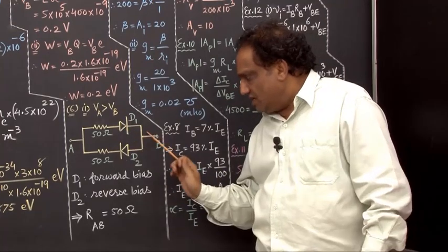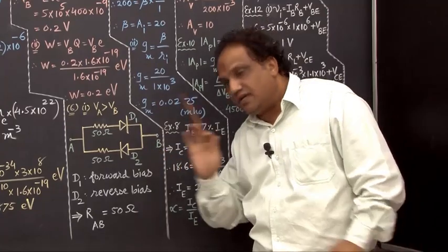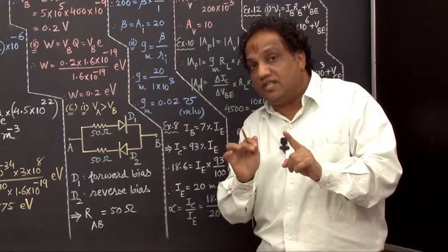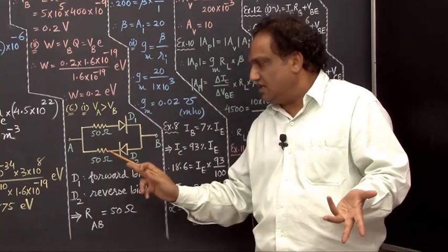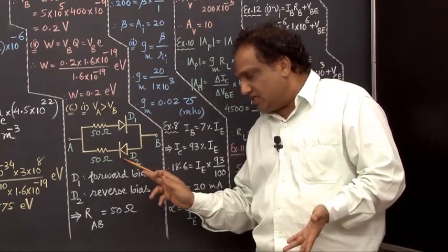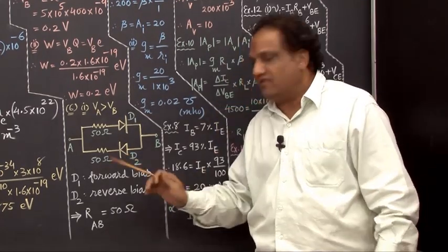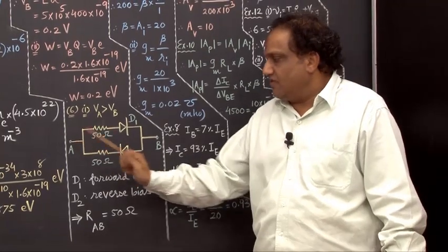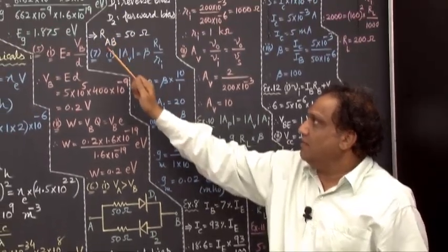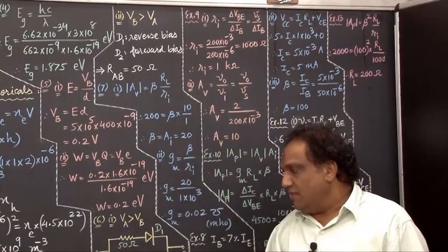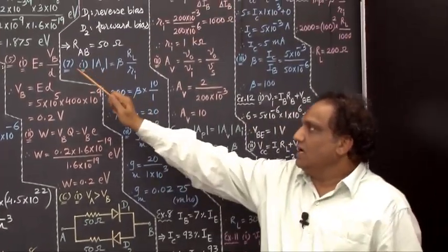Come on. When current is passing through only D2, it will have resistance in this branch only. So it will be offered resistance in this branch only. Come on, what is the resistance in this branch? You can see it is a series connection. But because this diode is an ideal diode, its resistance in forward bias condition is 0. 0 plus 50 will be 50. So again the equivalent resistance between A and B will be 50 ohm. So I am writing RAB equals 50 ohm, correct? Mind well, these two are ideal diodes, okay? Fine. Now read number 7.